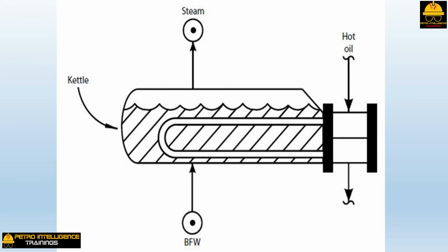This picture is the very common kettle-type waste heat recovery boiler. There is no water circulation. The tubes must always be covered by water. Allowing the upper rows of tubes to be uncovered will lead to uneven thermal expansion of the tube bundle and damage due to distortion of the uncovered tubes.